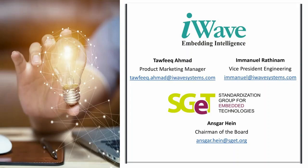Operating temperature is defined completely by the design. The companies can fix it based on the components used. As such, from the specification committee, there is no specific constraint. You can have industrial or you can have automotive, and even in automotive you can have much wider temperature. There is no specific temperature, whether it's size 0, size M, size S, or L. It's what kind of components you use and what kind of reliability level you want to bring in. It's up to the designer's choice, and the specification does not put any constraint over there.